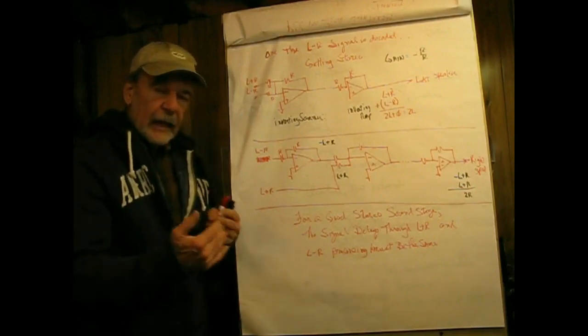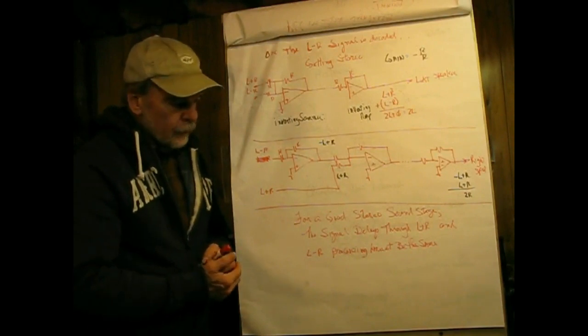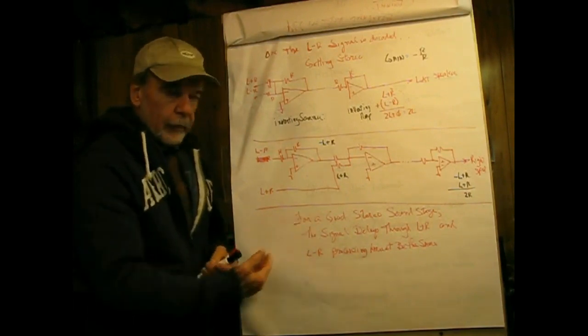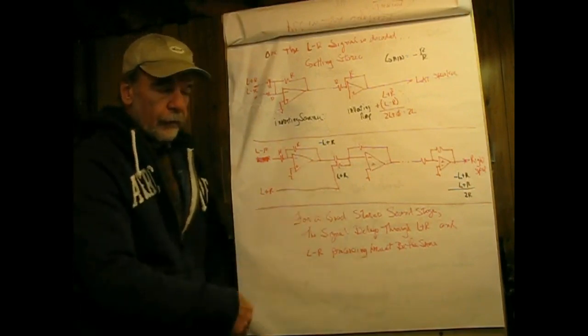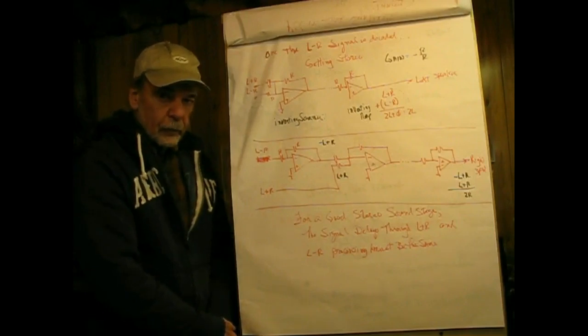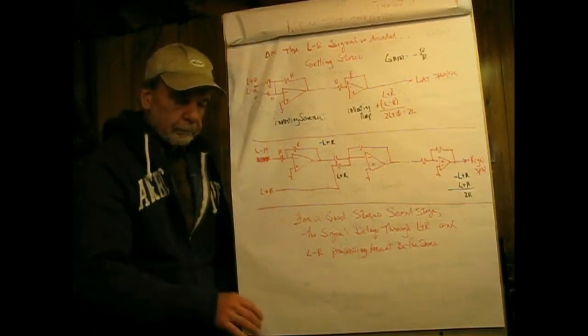And if there's any time difference, that stereo image disappears. So there are delay lines to slow down the L plus R because the L minus R has to go through additional processing. Under good circumstances, there will be about 30 dB separation between the left and the right channel.